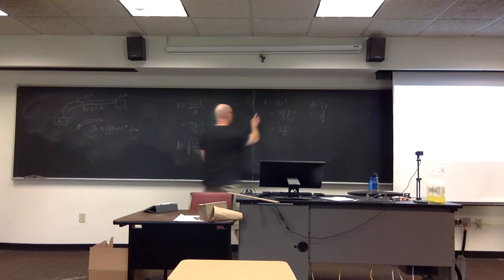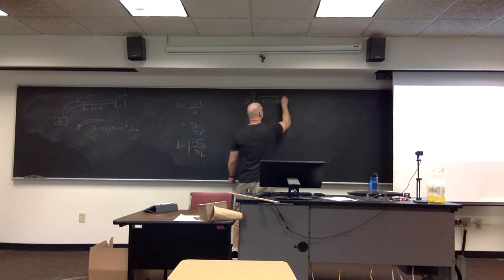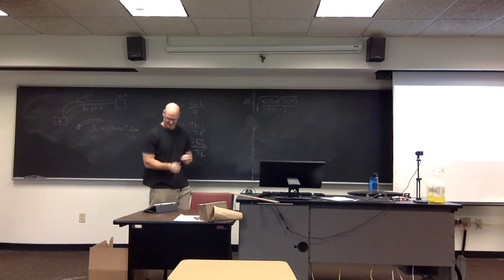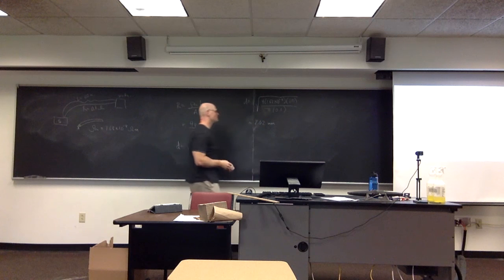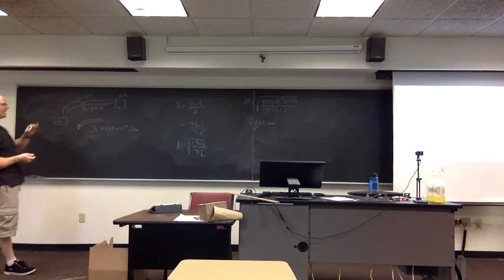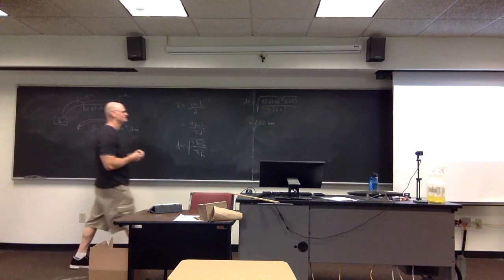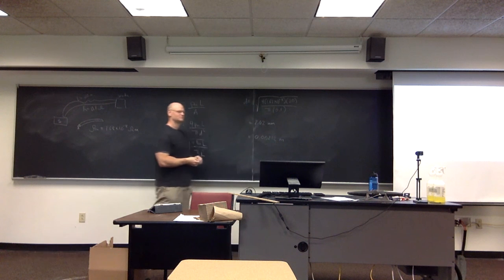Okay. So let's use this. Let's plug in our numbers. The diameter is equal to the square root of 4 times 1.68 times 10 to the minus 8 times the length, which is 20, divided by pi, 3.14, times the resistance, which is 0.1. What I find in this case works out to be about 2.02 millimeters. Notice the way it's written, the diameter would give it to me in meters, and then I'm just dividing by 1,000 to get millimeters. In case you multiply it out by yourself, you get 0.00202 meters, which I then put into millimeters.